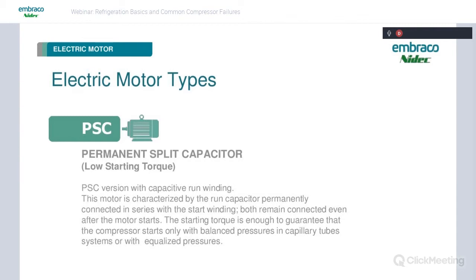Since we're talking about air conditioning, you're talking about a piston typically. A lot of your newer air conditioning systems are using TXV valves. So with this type of motor, you would need to add a start relay and a start capacitor if you had a TXV valve, or some of the TXV valves that they use for air conditioning are externally equalized, which helps the system equalize in the off cycle to get around that.